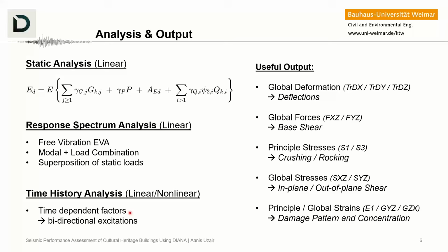If you define a load, if you define the time-dependent factors or the time history record in the load combination, then unfortunately you cannot combine them in a single analysis.